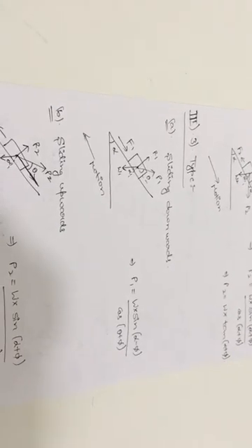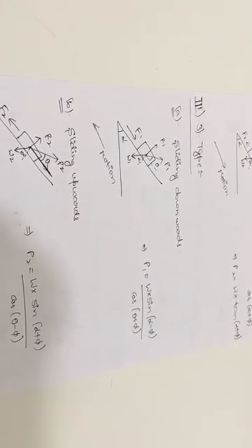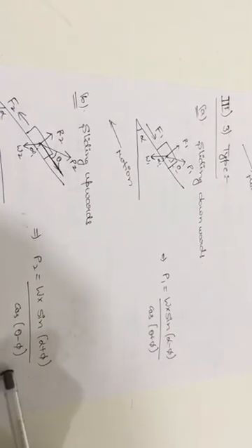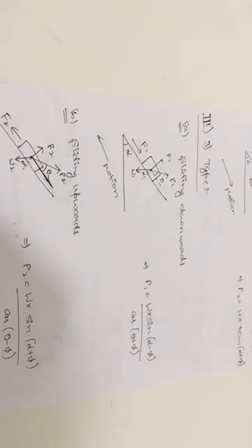You can directly apply the formula, or if you don't remember the formula, for that particular problem, if you apply sigma H and sigma V equal to 0, you can solve the problem according to the first unit, like resolution part and RCF diagram, rectangular components force diagram, and from that if you apply the equilibrium conditions, you can solve the problem. If you remember these formulas, you can apply the formula directly. If you don't remember these formulas, you can solve according to the equilibrium conditions.